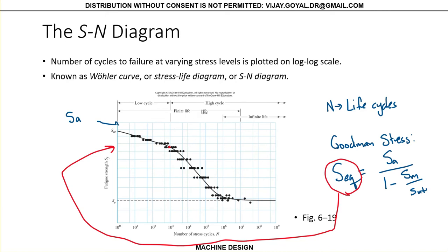Also, high cycle fatigue is a lot more mature than low cycle fatigue. Your plot is coming from a point right here, ultimate tensile. And then you have a point right here, what we're going to call F multiplied by SUT. And what is that factor F? We will talk about that in the next couple of slides. Just hold on to that thought.